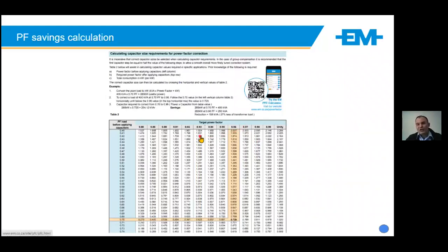What I do tell some customers is to make a shortcut on your phone to this link, which you just add to your home screen. If you're in front of a customer and you've got the meter data in front of you, you can quickly give them an estimate of the kVAR required for the site. This calculator will only give you the kVAR required. It does not know whether I need reactors or filters and so forth. And that takes us to our next topic.